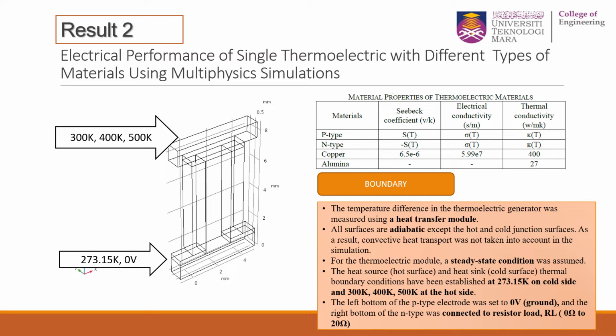The boundary for this simulation is the temperature difference in the thermoelectric generator was measured using a heat transfer model. All surfaces are adiabatic except the hot and the cold junction surface. As a result, convective heat transport was not taken into account in the simulation. For the thermoelectric model, a steady-state condition was assumed.